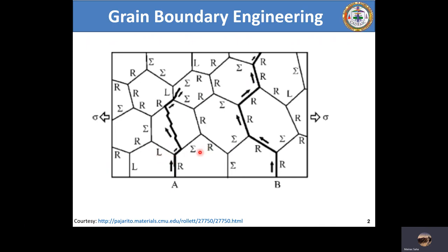What we instead would see in an actual microstructure is an R and a sigma here, and so the volume fraction of sigma has to go higher up, as compared, and the volume fraction of this R in the given section of a microstructure has to come further down. And of course, in that case, we would see that the microstructure gets more resistant to crack propagation.